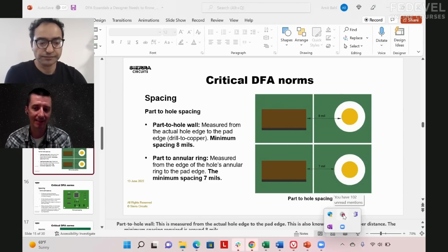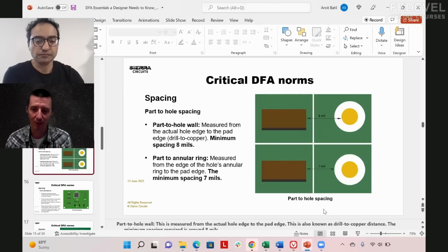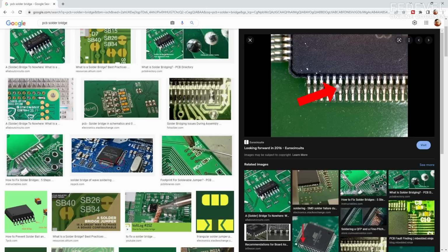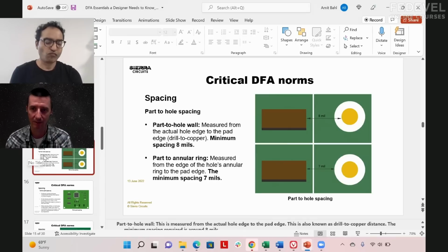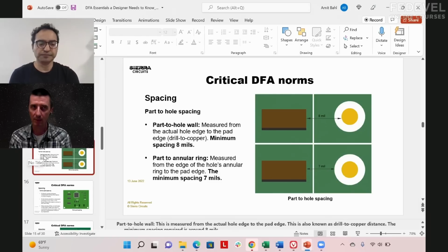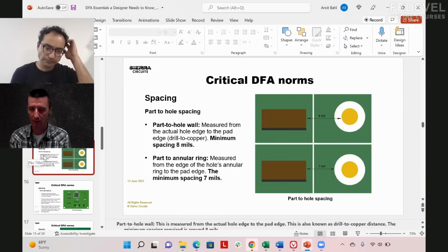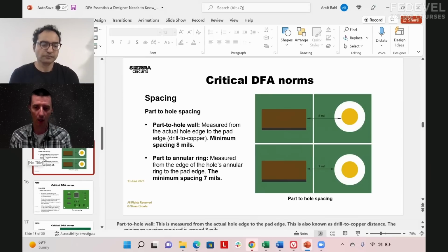How bad is it then for the solder bridges? Is it much worse? Yeah. So the solder mask is really helping to prevent creating these solder bridges? Yep. But sometimes this is difficult because sometimes the pads are very close to each other. So does it mean the designer should always try to keep the solder mask, even at the cost of making the opening almost the size of the pad? Absolutely. Yes. Okay. And what is the minimum opening around the pad? Do you know the standard minimum opening?